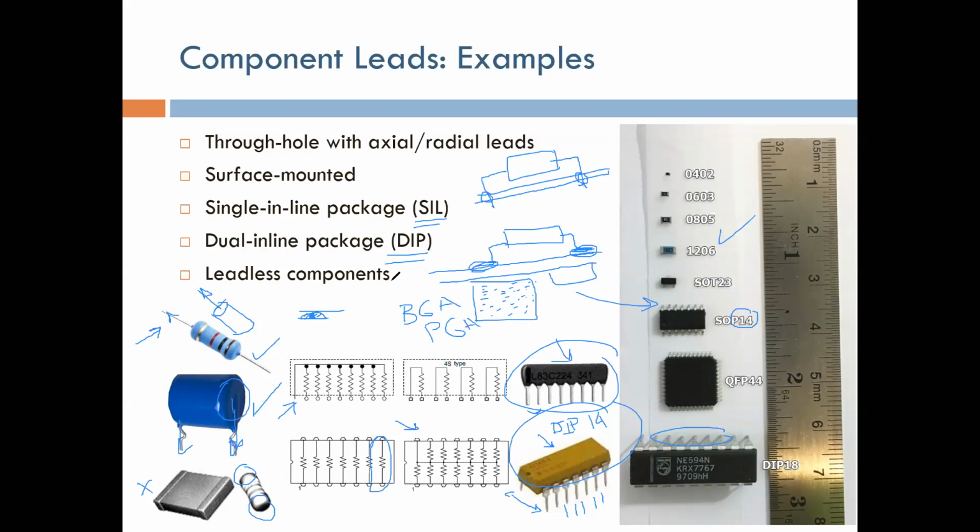Maybe the first time I started with my students in my projects, like 20 years ago, we usually ordered the components that we found online, and we didn't care much about which package we ordered. And this was a problem, because if you get a component that looks like this, it's going to be really difficult to use it on a breadboard. It's almost impossible. You have to solder wires to each one of these leads in order to be able to use it.